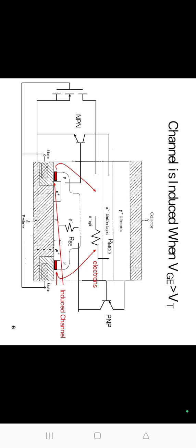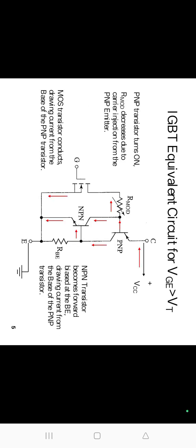Hence, structure of IGBT is organized such that body region resistance is very small. If R1 is very small, then T2 will never conduct, and equivalent circuit of the IGBT is shown below. This is the equivalent circuit of the IGBT.